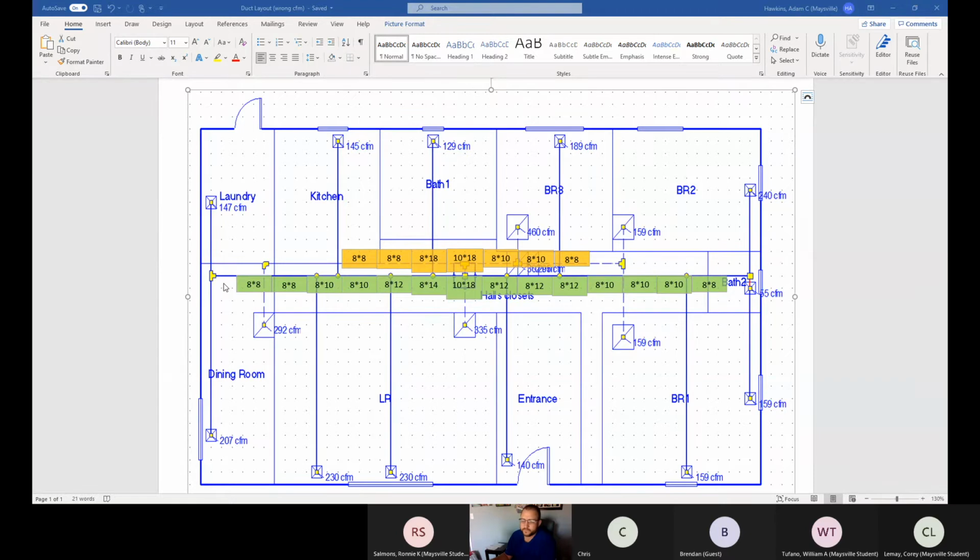Does that make sense? And so you're just slowly reducing the size of the duct to try to keep your static pressure the same. Because as you take vents off, there's less and less air that's needed, but you're trying to keep that whole system under a constant pressure by reducing the volume. Because if you just say, I'm going to run everything exactly the same size, and then you start shooting ducts off the side of it, if you really don't know what you're doing, those end runs are going to suffer because there's not enough pressure to push those end ones.